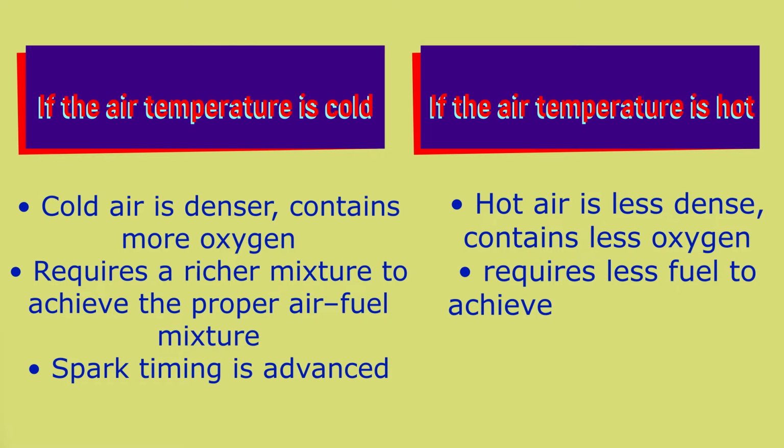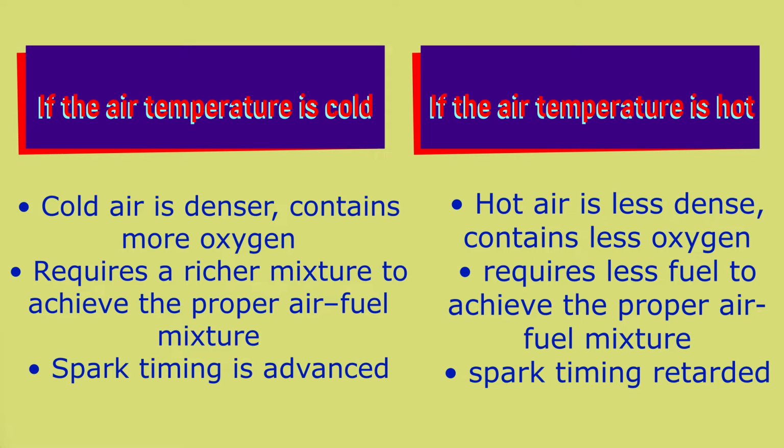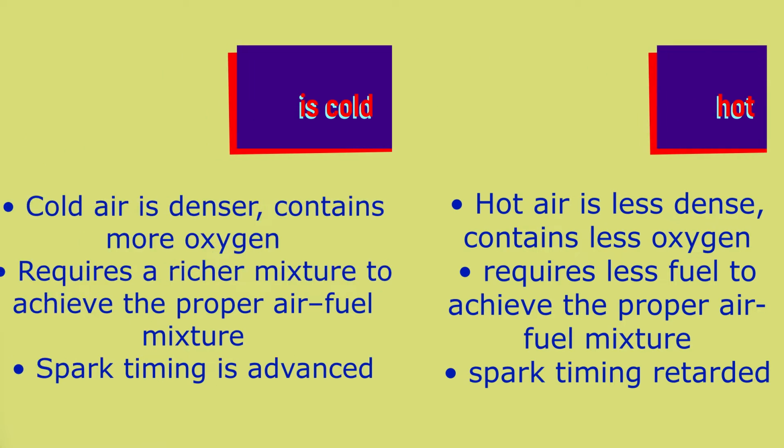Cold air is denser, contains more oxygen, and therefore requires a richer mixture to achieve the proper air-fuel mixture. Hot air is less dense, contains less oxygen, and therefore requires less fuel to achieve the proper air-fuel mixture.